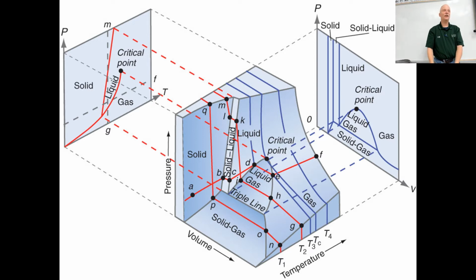So these engineers have figured out we have to build it bigger than we need it. They use the engineering calculations for what's going to happen to that steel in the solid region, under that kind of pressure. What's the new dimension going to be? That's the dimension we need to aim for. So they build it differently than it will be when it's installed.